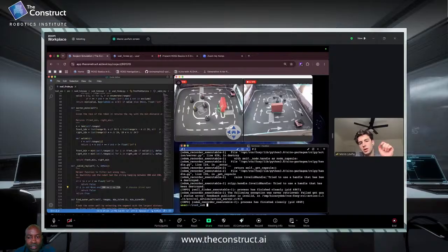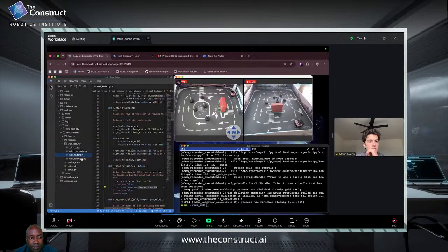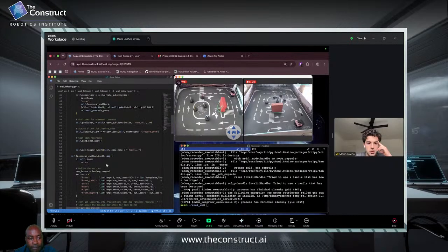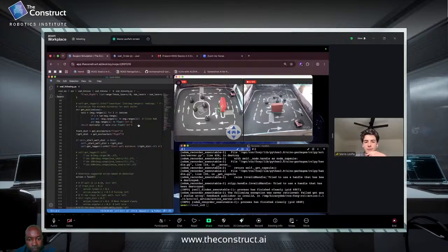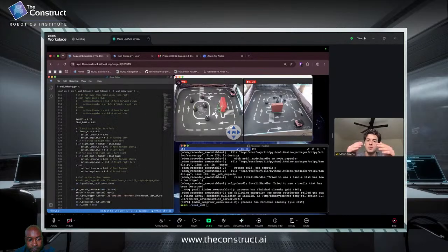I'm using mostly an if-then-else controller. Essentially, it's a very simple command where there are two things that we take into account: the distance to the right and the distance to the left. If we get very close, let's say it's here right now, turning a corner, and we get very close to the center wall, then we start turning left.